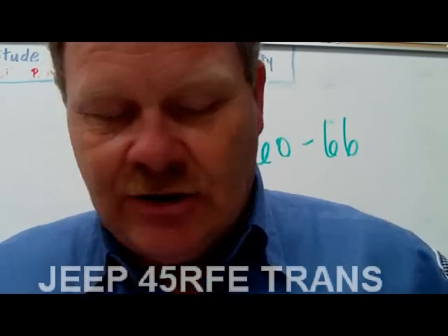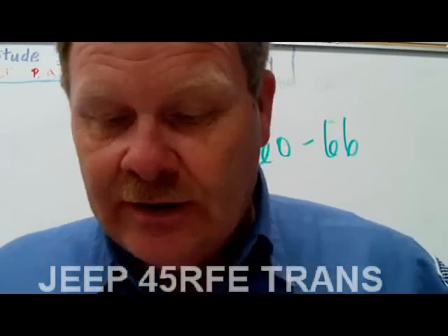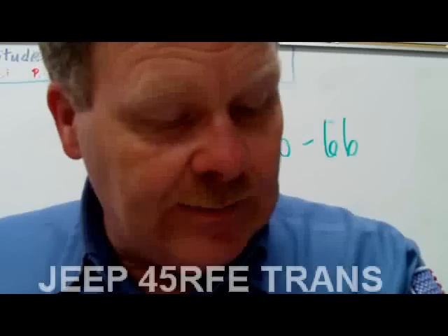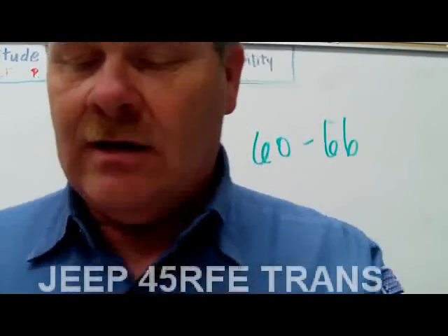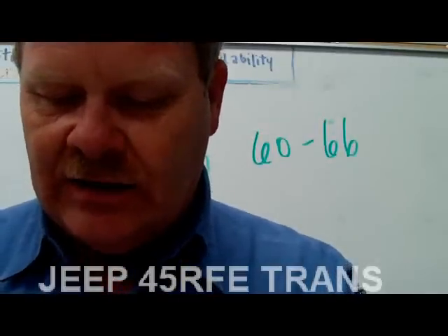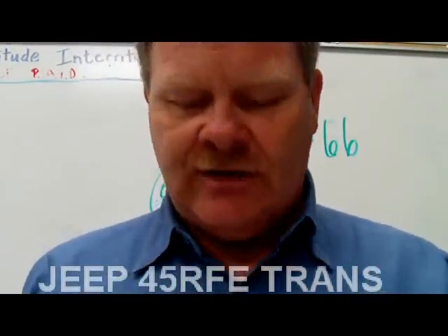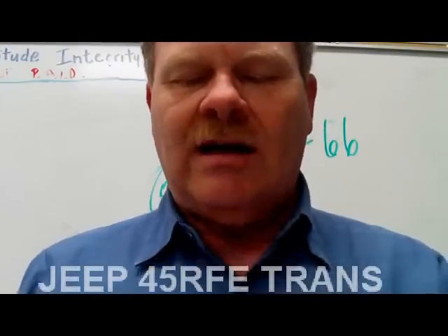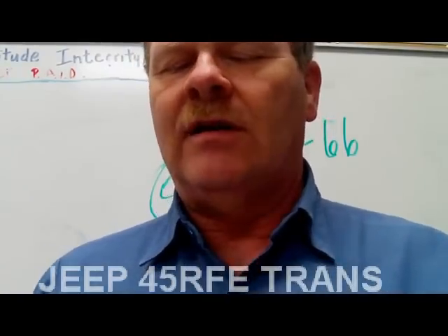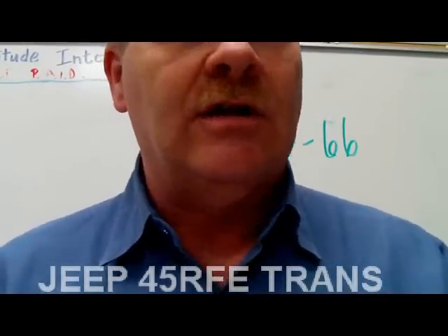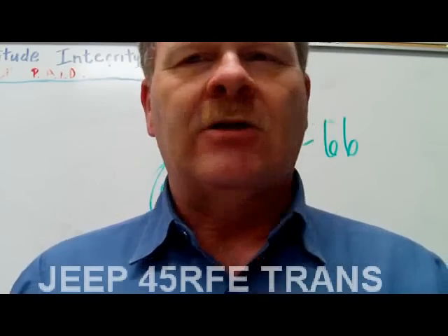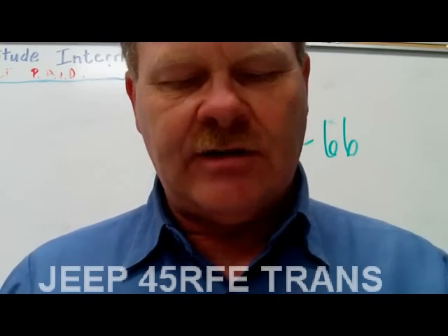See, all right, we're going to run across a number here in a minute. You keep paying attention to them questions. If there are some that you didn't get answered when I'm through telling you about this, then we'll go through that. But we're talking about a specific transmission here. Torque management means it reduces the torque that the engine is putting out at the point of the shift, and it makes it feel smoother. Because a smooth feeling shift is what it's all about.